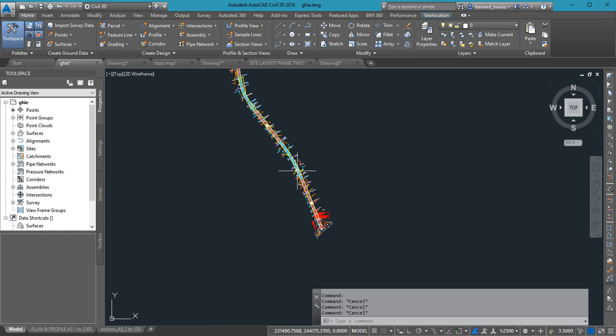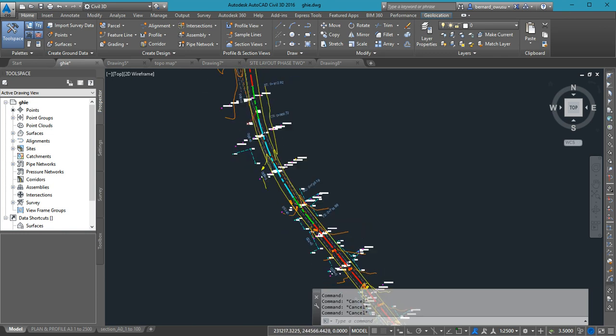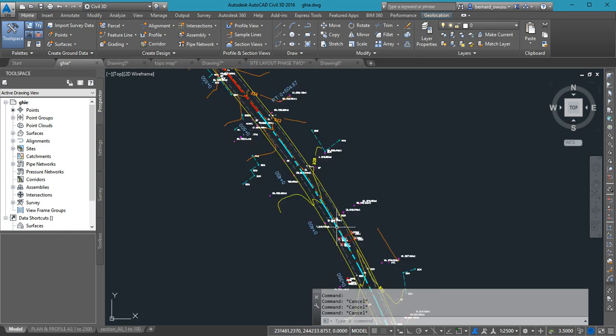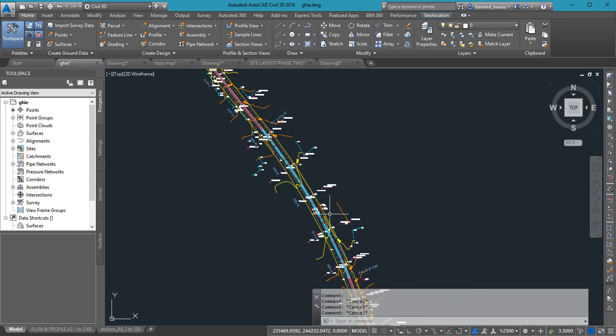You can confirm and you see it's less than 360. Also, if you have a warning on a curve, the arc, it means that either your radius is below the minimum or the length is also below the minimum length. The minimum length, you can get it from the design guide. What the minimum length for a design speed of say 60 should be.